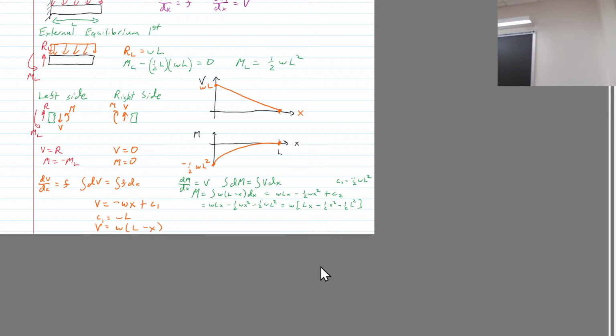So these are the contributions from PY. Yes, we identified tau T, that was from torque. Tau V is, like we said, the bending, it's a transverse shear stress. And then there's no bending stress because, look, it wants to bend. Imagine you move PY over here, that would be causing this to bend like this, and if it's causing it to bend like that, and this is on the neutral axis, there's no bending stress.